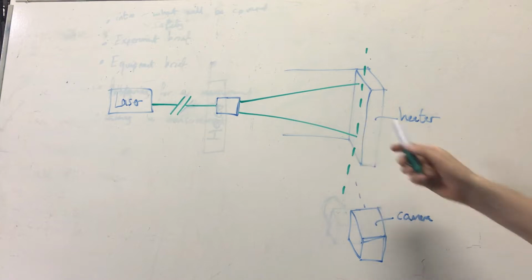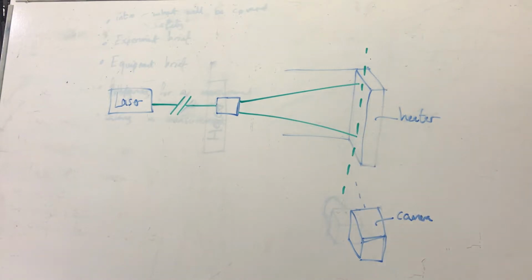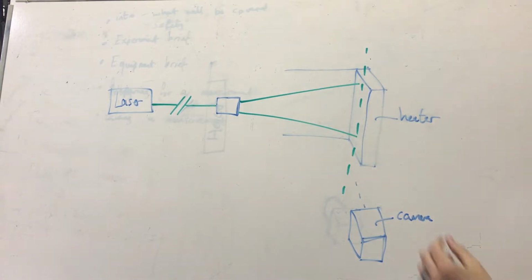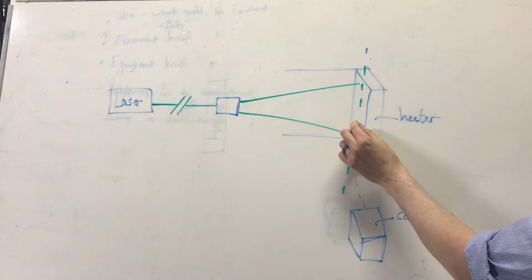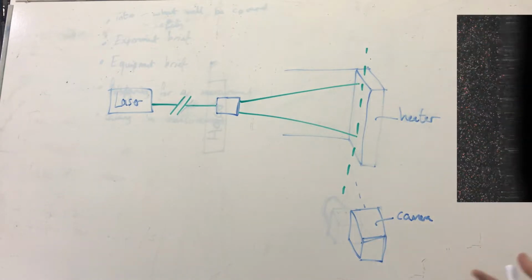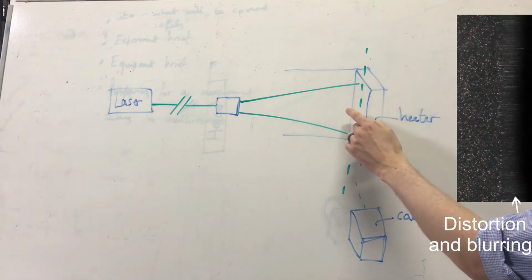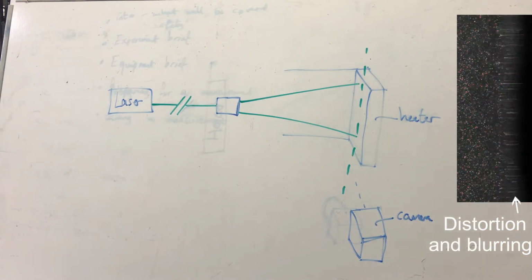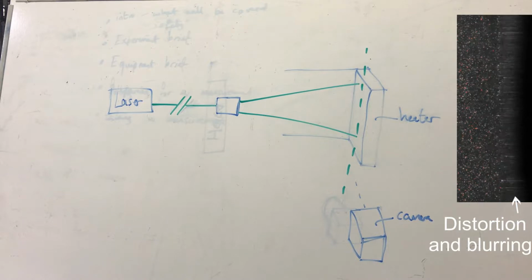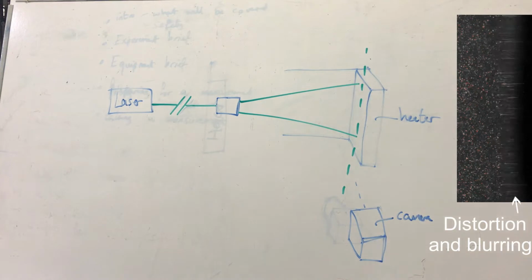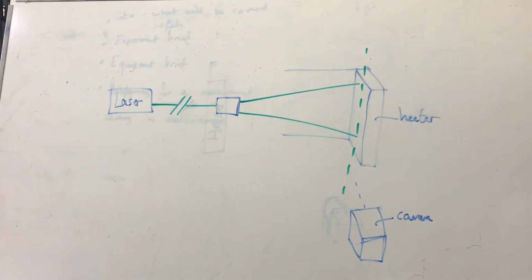One of the reasons that this is a particularly tricky application is because you have this large difference in temperature near to the surface as a result of transferring heat and therefore producing density, but at the same time that change in temperature changes the refractive index of the fluid near to the surface, and so what effectively is happening is the water near to the surface is acting like a liquid lens, which is distorting where all of these particles are appearing to be. And the purpose of that other technique, background orientated Schlieren, or BOS, is to correct for that distortion so that the PIV measurements can become more trustworthy and used for validation.